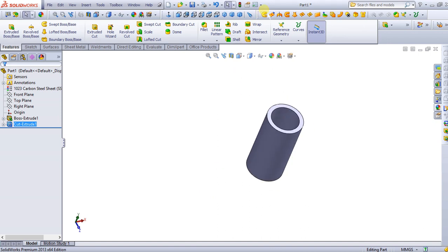Now you have not saved your part. When you design, you must be able to save. Solidworks is very flexible and very good, so that if you are designing a part, it will remind you after 20 minutes that your model or your part or your document has not been saved for at least 20 minutes. So as you start your sketch, you must save first.